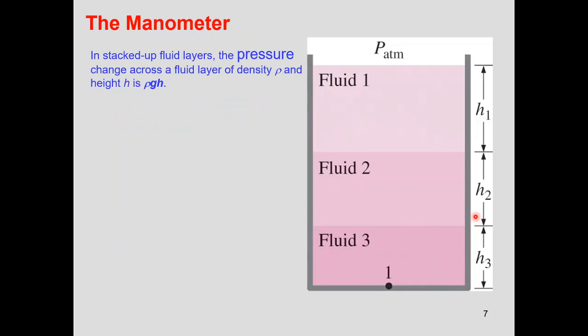How we use a manometer is still the same way, the same equation, P equals rho g h. A simple manometer uses only one or two types of liquid, but some manometers use more than one type of liquid. The solution is simple. You know that P equals rho g h. So no matter how many layers of fluid are used, you can just add the P equals rho g h level by level to get the total P.